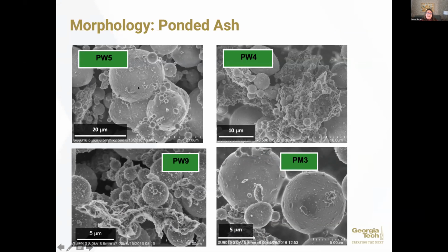You can see that we've got precipitation of additional mineral phases on the cenospheres that we have present as well. Some amorphous phases we've found within these ashes. You can see what looks like visual evidence of those too. The other thing that's interesting, if you look down here, you can see that we've got this meniscus that has dried out. These are SEM images, so the samples are dry. You can see that as the meniscus dried out, we precipitated additional mineral phases here in the lower right-hand corner, which are connecting particle to particle.